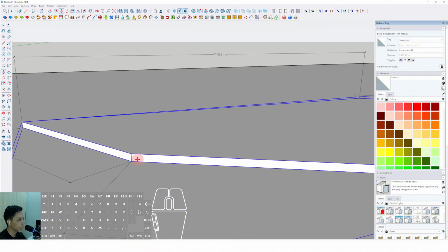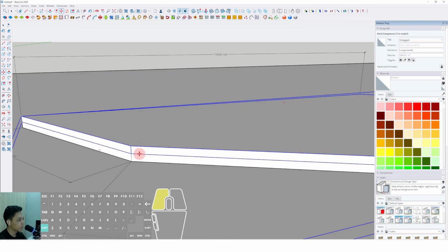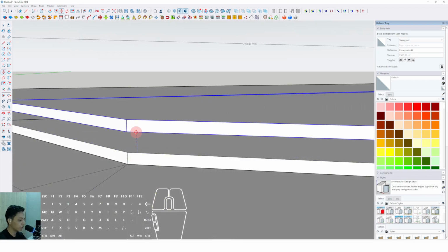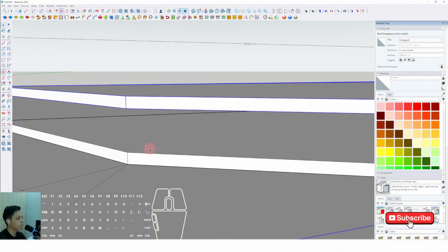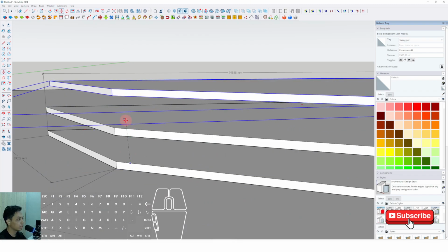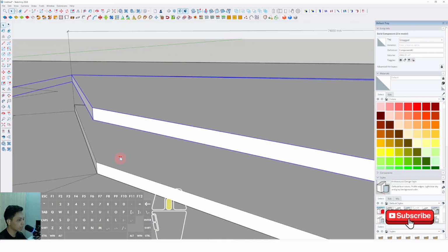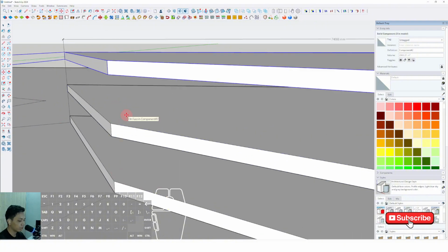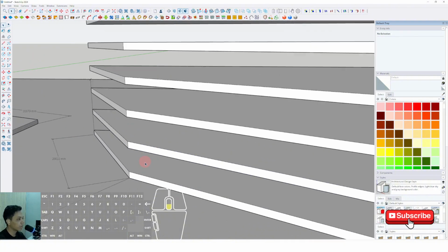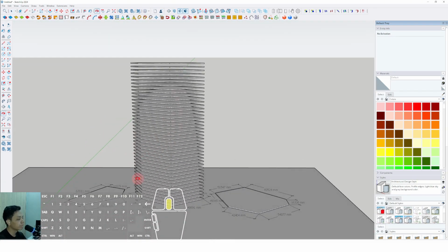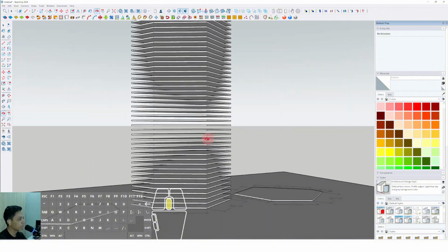We have to move and duplicate to this position. Then we can set the floor to ceiling around 3.6 meters. Okay, then we can select move, press Ctrl, and place it above. Then we can type X40 and enter, and we automatically get the basic high-rise building meshing here.